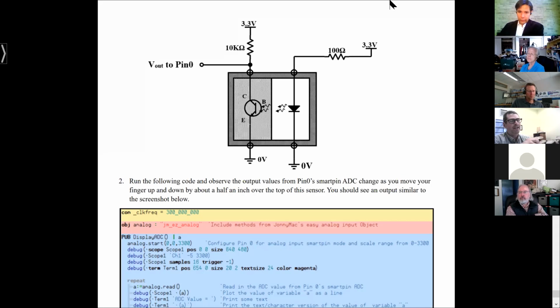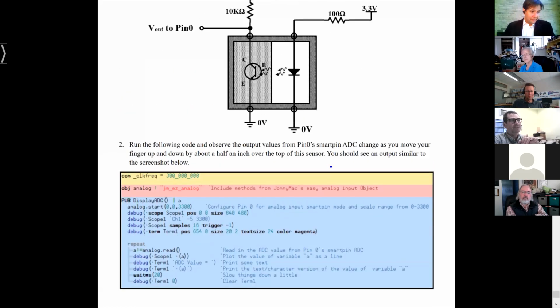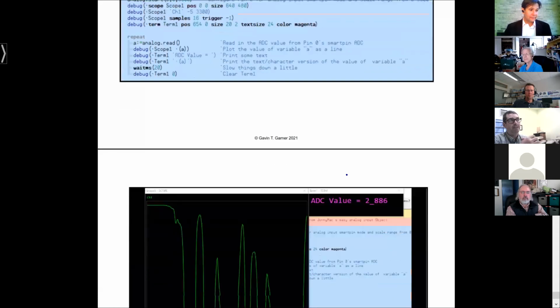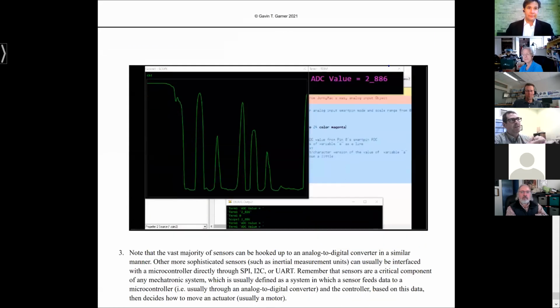What was the bandwidth he was getting off of it? I think he said something like it was over 10 megahertz. I want to say 20. Oh, wow. Oh, cool. Okay. Yeah, I'll have to check that out. That's going to be cool, because particularly for oscilloscope mode, that would be pretty neat. Yeah, the trouble is with our normal ADC, the analog front end limits you to maybe 2 or 3 megahertz before it starts to attenuate.